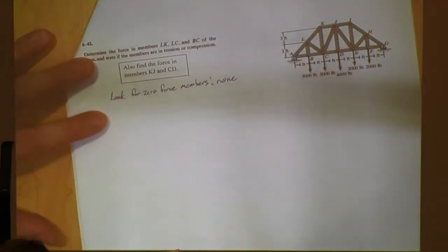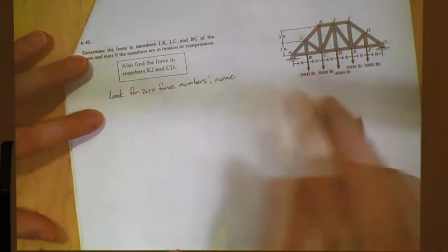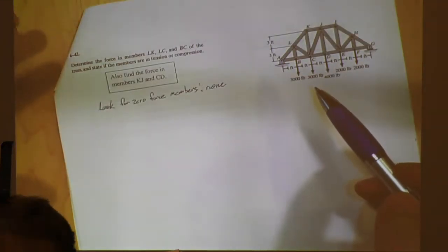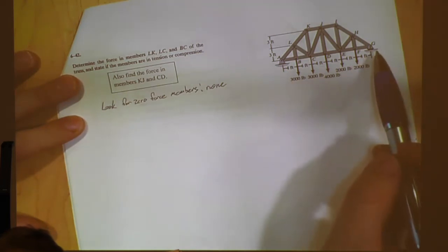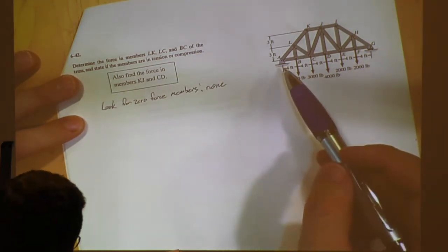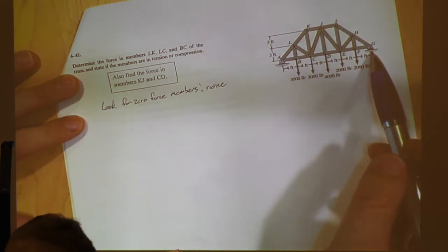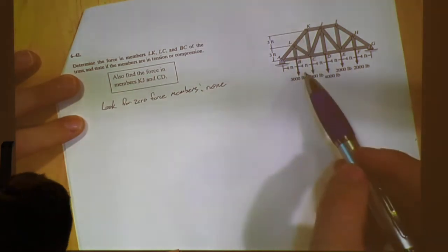All right, next step it would be support reactions. So how do we get our support reactions? What do we treat the truss as? We treat the truss as a rigid body. This allows us to actually get the reaction forces in G and A. But do we need the reaction forces at G? No, why? Because we can cut straight through.